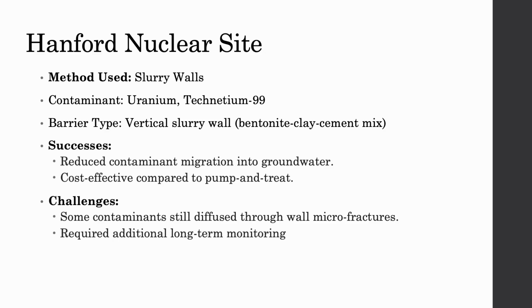And so this case reminds us that even effective barriers need backup plans, monitoring, and sometimes reinforcement as well. So an important lesson from the Hanford nuclear site is the role of site-specific geology. So the success of the slurry walls depended heavily on uniform soil conditions.